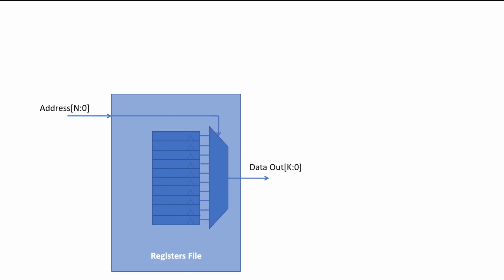Well, a mux can be used here to do the selection job. For writes, we want to write data into a specific register specified by the address only if the write signal is 1. Pause and think about it too. Well, we can broadcast data in to all the register inputs and demux the write signal to all register enables.